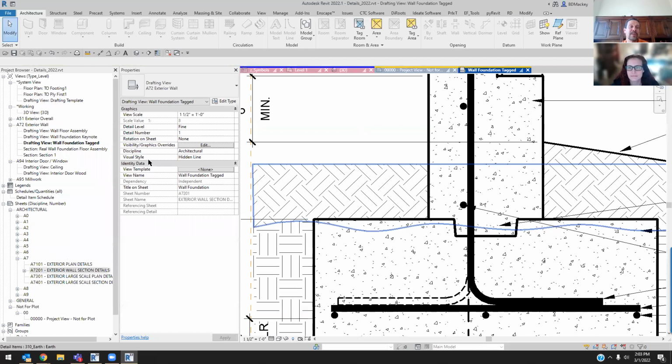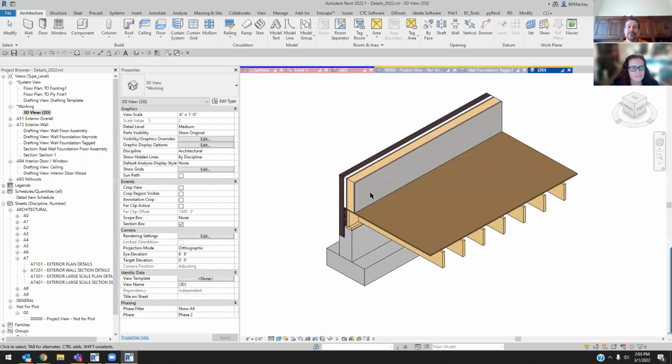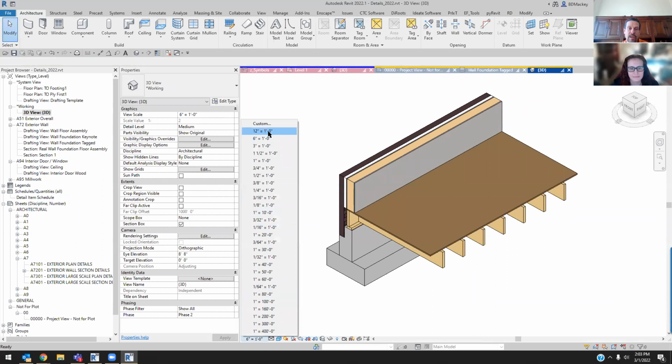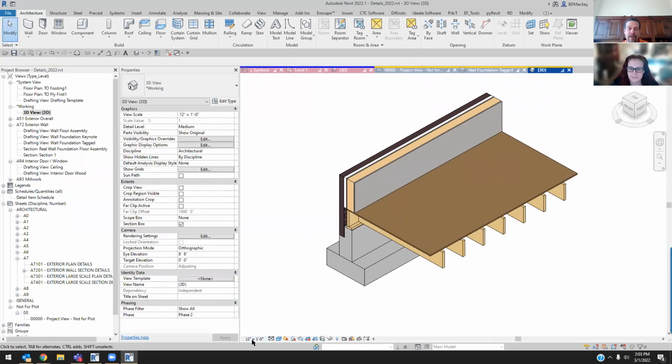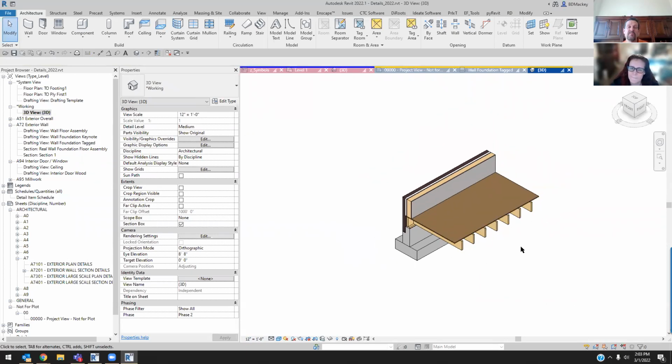I will say I did learn something this week that I was going to talk about and come back to. Did you know when you're exporting out, the scale matters when exporting to DWG? I had a client who was literally trying to export out a building that was 50 feet by 20 feet. And it kept saying, the file is too large. We're like, it's a 50-foot building. I've exported out buildings that were 6 blocks long. She had the scale at 12 to 12. We went back and changed the scale to something small, exported just fine.